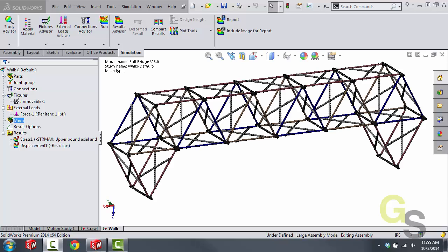Now that we've cleaned up the joints a little bit, the model looks a lot better. Now again, the reason why we were doing that was because the connections between some of these beams are entirely rigid. That means that they don't flex at all. And this, remember, makes the model much stiffer than it actually is.